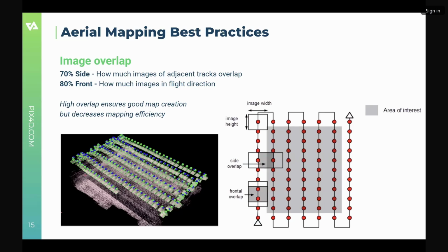Yeah, I would say, generally speaking, in the fast mode of Pix4D Fields, you can have a lower image overlap setting and get away with kind of murder, because of the way that mapping algorithm is working. So you guys can push that. I've heard some of you say you've pushed it as low as 20%, or like you mentioned, 30. I don't know if I would advise 20 or 30, but I would say 50 sounds possible. You're going to see some more artifacts in the image, which are just those distortions because you're seeing the sides of things. But for the most part, it's going to work for your types of uses.